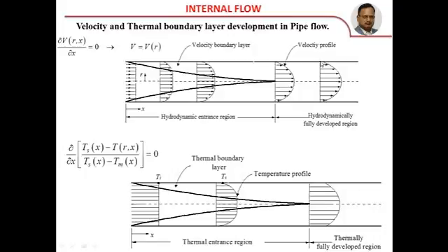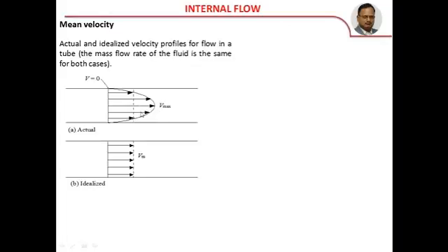Now if you observe this figure, the velocity is gradually changing. The velocity is 0 at the wall, increasing and reaching a maximum value, and then again reaching 0. So to determine the Reynolds number in this, you have to use the formula ρvd/μ. Which velocity should I consider? So I have to find the average velocity of the fluid, or mean velocity.